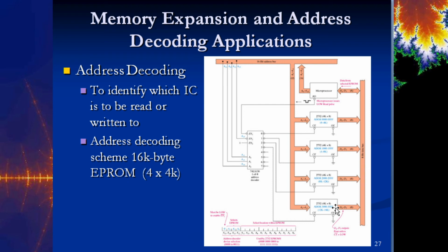So if you've got more than one here, you can see that the enable signal is coming from the microprocessor, and we have the address on the address bus here, and so that's going to get passed on, and we're only going to turn on one of these. So we've determined that this address is, I assume, 000 here. Yes, it is. And so this is the next memory address, the next one, and so depending on which address is on the address bus, this will decode and turn on the appropriate memory that we're supposed to be accessing at a particular time.